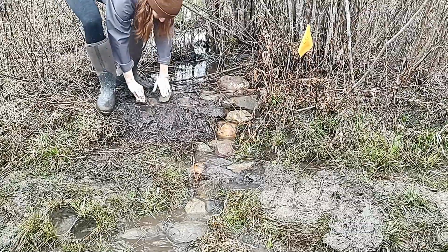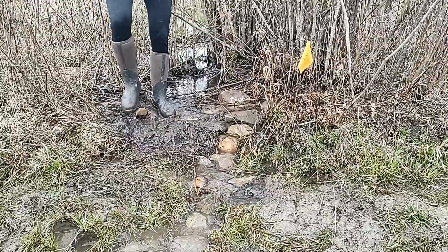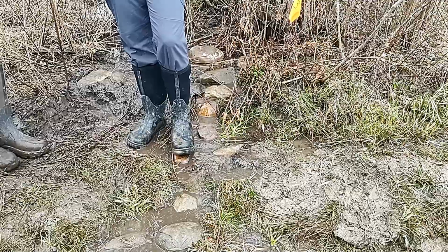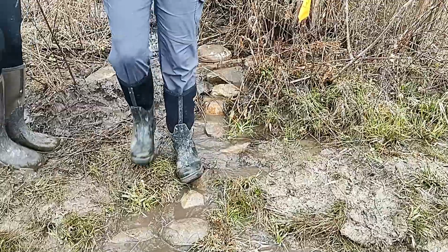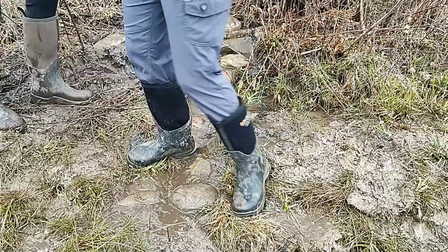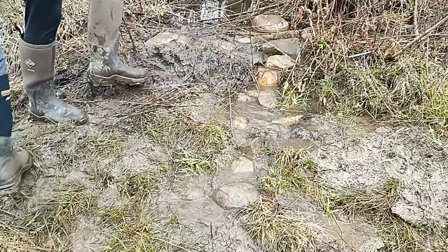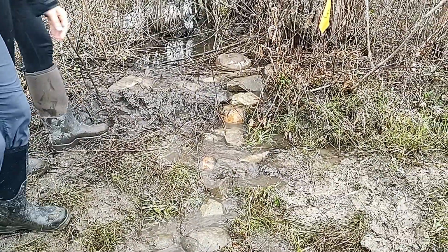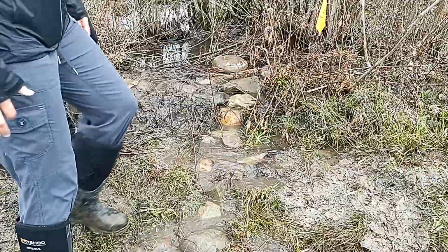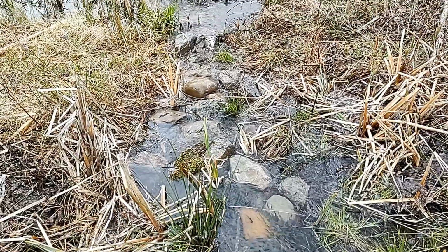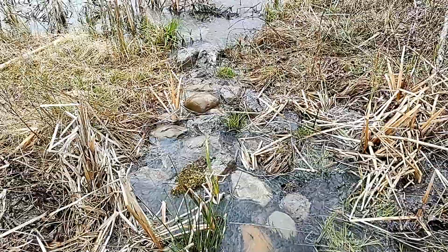We decided to repair the spillway by hand instead of waiting to bring in heavy equipment. We gathered rocks from the surrounding area by hand and placed them on the ground where water was flowing. We then used our feet to push the rocks into the ground. We used our weight to create a wider floodplain for the spillway. Water is now spreading out and flowing over the rock in this maintained spillway.